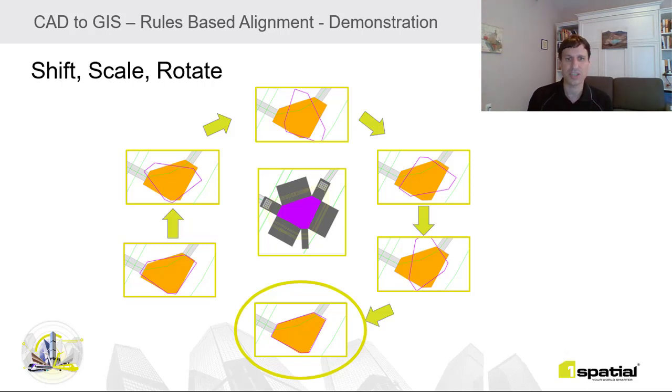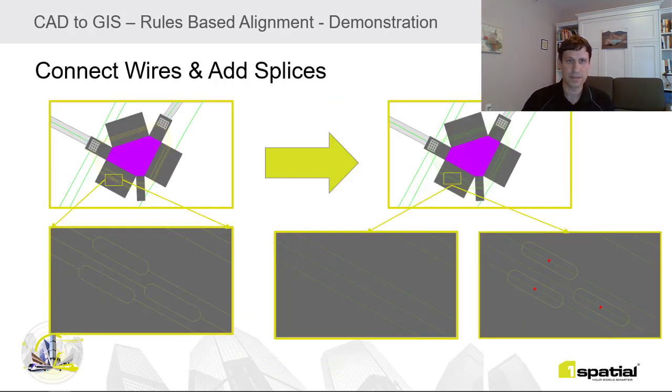However, we still must address that this is only a schematic representation. At this point, the data is not ready to perform geospatial analytics on the feeder lines. So the next step is to turn the schematic into the actual geospatial representation. So next, we identify the splices within the feeder lines by finding where the feeder bifurcates. After identifying the location of the splice, we can replace the bifurcation with a straight line, and then place a point identifying where the splice occurs in the feeder line.